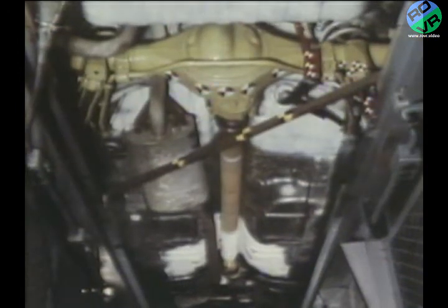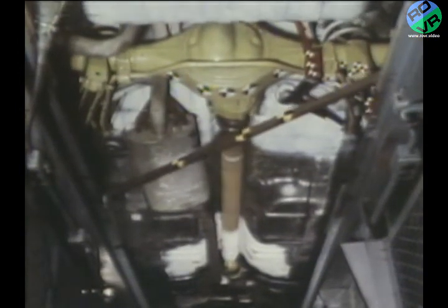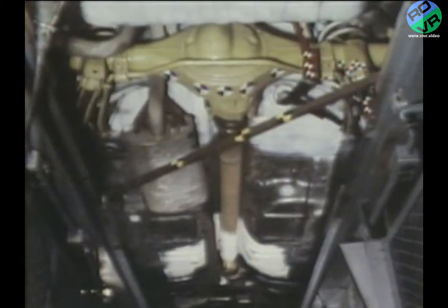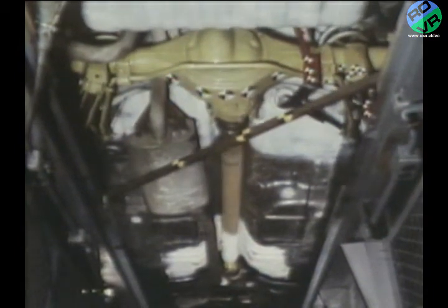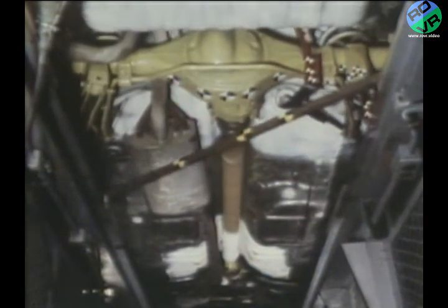Since the driveline is located close to the floor pan, the pan tends to move with the driveline. This movement of the driveline and nearby sheet metal acts like a drum. We can see that an unbalanced driveline can cause an objectionable condition that is often described by the owner as a drumming or booming sound.